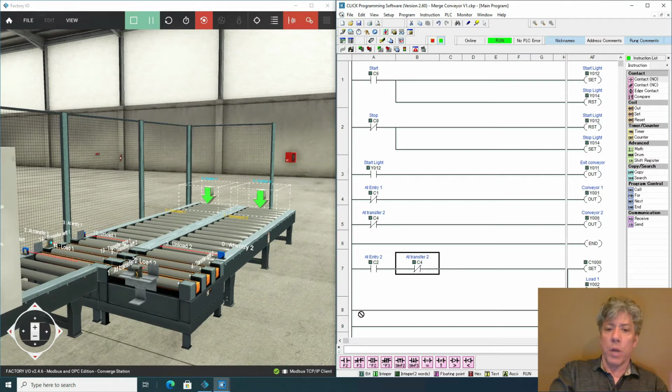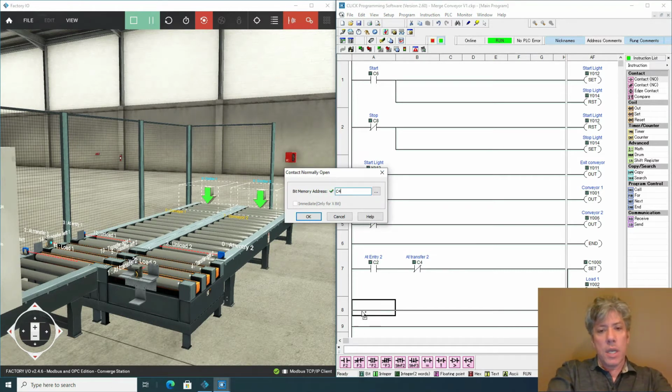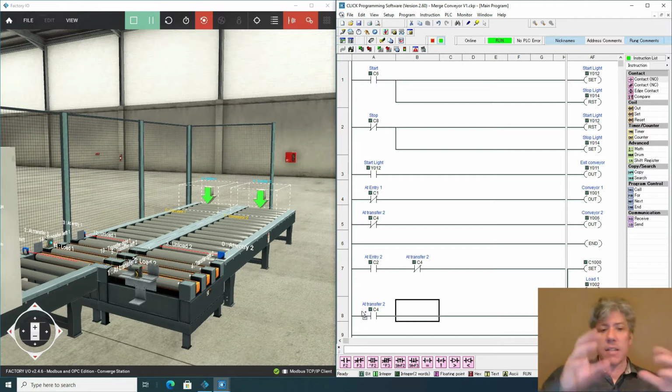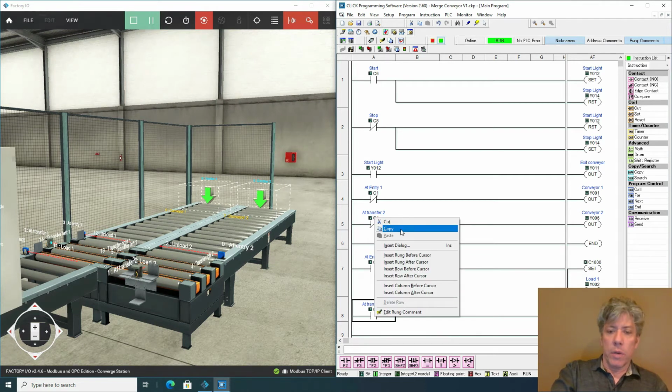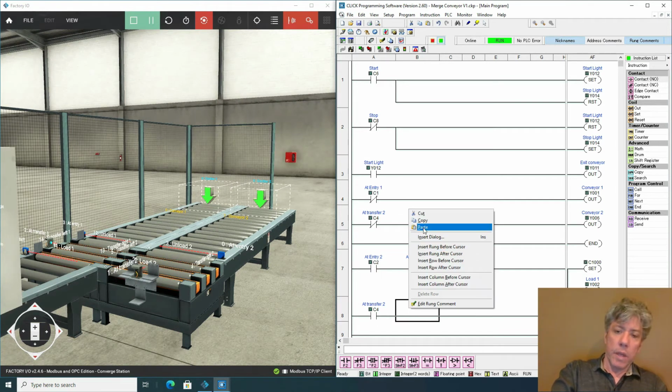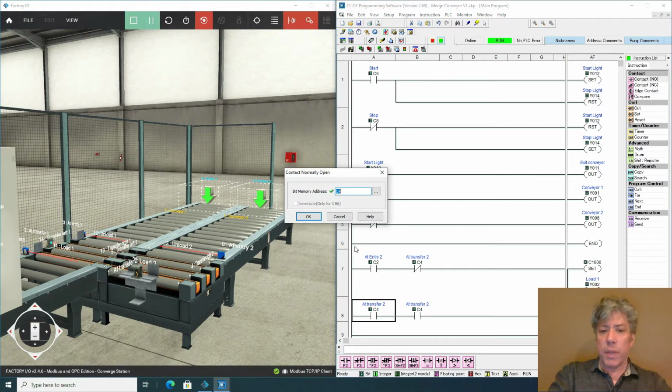That sensor will be true. So let me put that condition next, C4. But that sensor being on by itself is not the only thing that's important. I need to remember that this has happened after I saw that there wasn't one there. So a bit that I'm going to add here as a condition for the next event memory, let me copy this, that'll be the quick way, copy it and paste it, is that there's something special about the at transfer 2 going true, that there's a conveyor there now. It's that it happened after the event of there being nothing there.